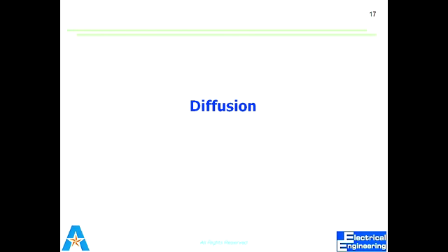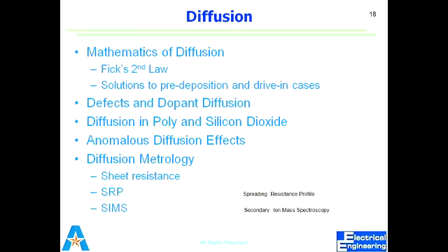Doping is also one of the very important processes, because doping actually affects all the other processes in fabricating the device. Doping is done by 2 techniques, either by diffusion or by ion implantation. That is, you bombard the ions, or you diffuse your dopant through the diffusion process.